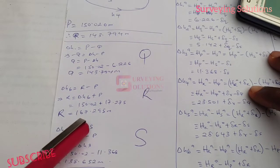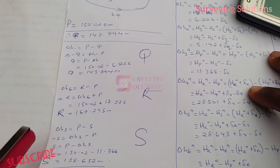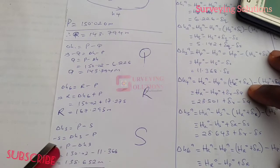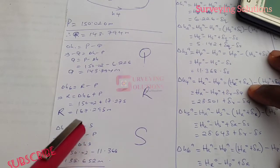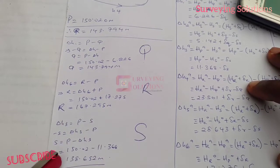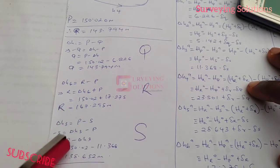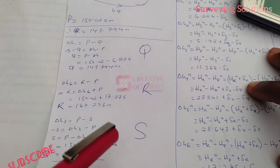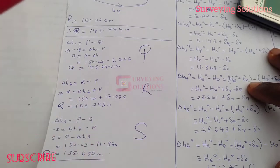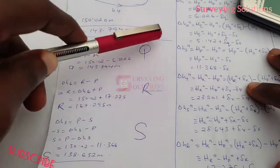So our minus S, because this S has a negative sign, will actually be change in h3 minus P, because it's crossing over to the other side. But what we need is a positive value. So when we use the minus to multiply through the equation, we have S equal to, this will change to negative and then this will change to positive. So we have P minus change in h3. So our P is constant, then the change in h3 given to us from the question is 11.368. So 150.02 minus 11.368 will give you 138.652.